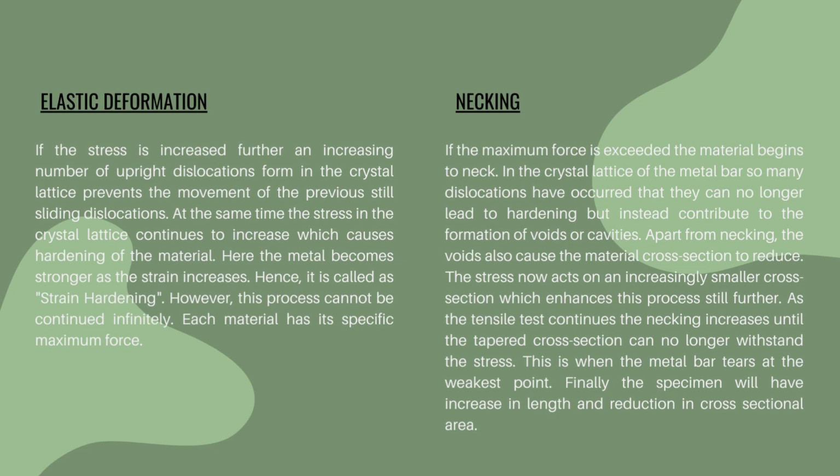After UTS, there is strain hardening. If the material is loaded again, the curve will follow back with the same elastic modulus, which is the slope. The material now has a higher yield strength. Raising the yield strength by permanently straining the material is called strain hardening. Lastly, we have fracture. If the material is stretched, the stress decreases as necking and non-uniform deformation occur.